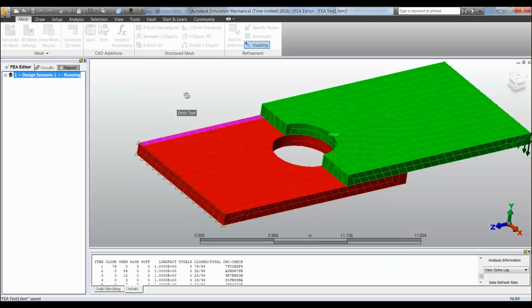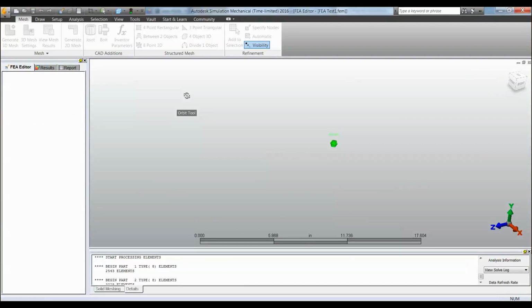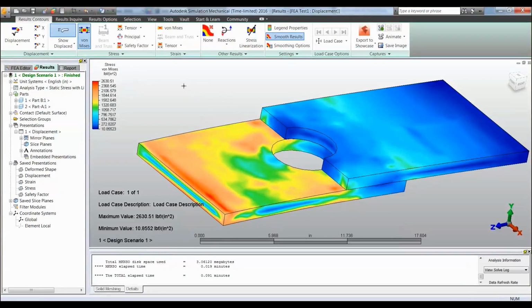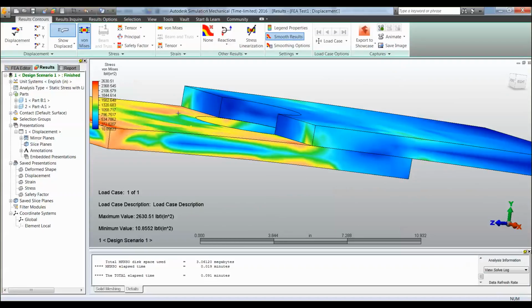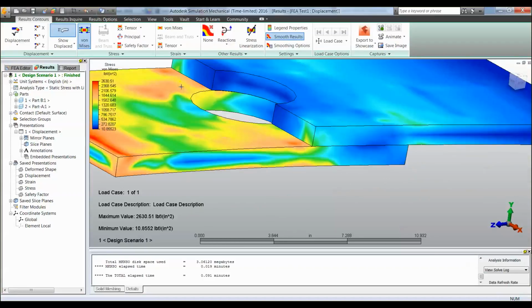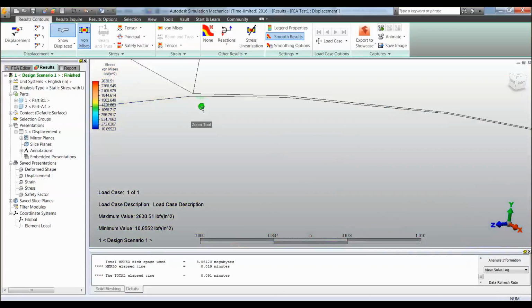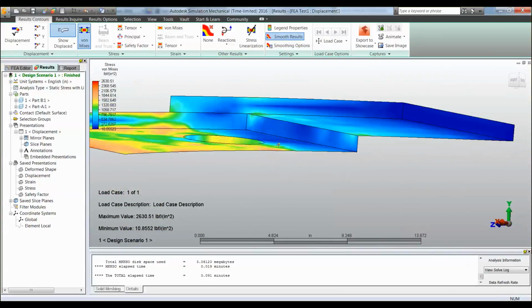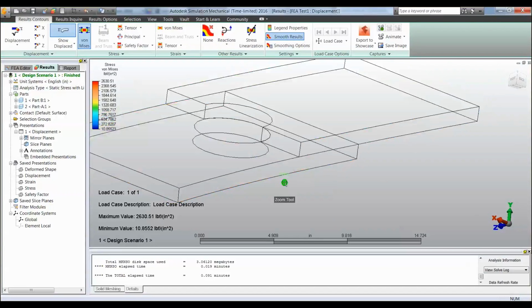So that way we can control this more as a weld down the sides of this thing and see what it looks like in there. There we go. So you can see a little bit more stress on those sides where we actually have it bonded in there, where in here we're actually getting a lift off, where it's lifting away from that face in there. Now if that was the only weld that's put on there, it's pretty accurate in there, so you can see the representation of where those were being held at in there.